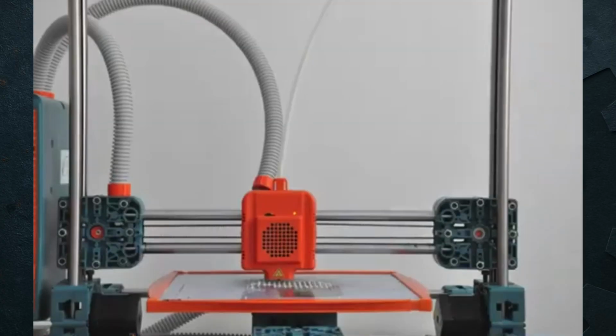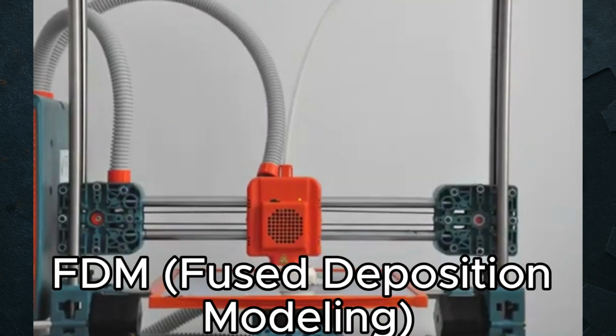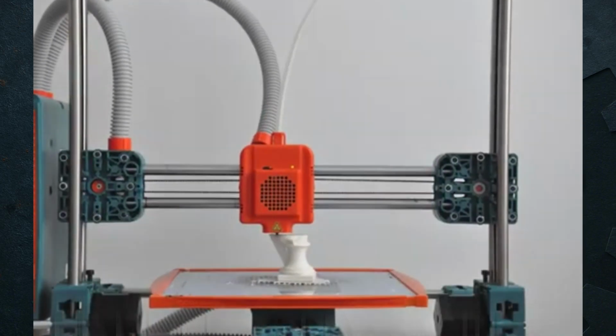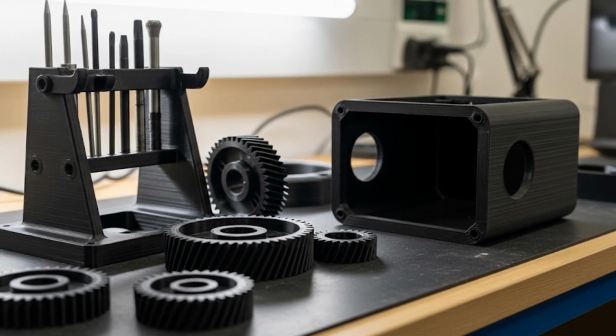The most popular form is FDM, or fused deposition modeling. This process melts plastic filament, like PLA or ABS, and deposits it through a heated nozzle in thin layers. It's affordable, fast, and widely used for prototyping, DIY projects, and even custom tools.